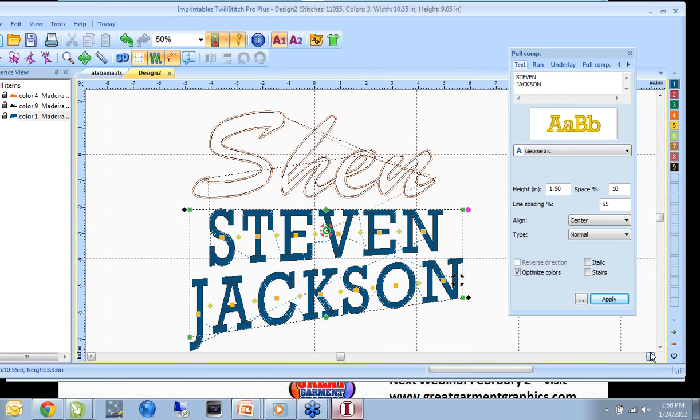Okay, I just have a couple more quick ones. Sure. Since you're a laser engraver, to cut your applique, how do you adjust your depth for that 3-layer design? It's in the software with the individual laser. The particular unit you saw there was a Universal laser, and on that one it has an automatic setup to do 2-layer. You could adjust it to do 3 or more layers manually by doing 2 layers at a time. The biggest design I ever did with layers was one that was 5 layers deep, just to see if I could. It was a little tricky, but it did work out. So that's part of the software that comes with the individual laser engraver.